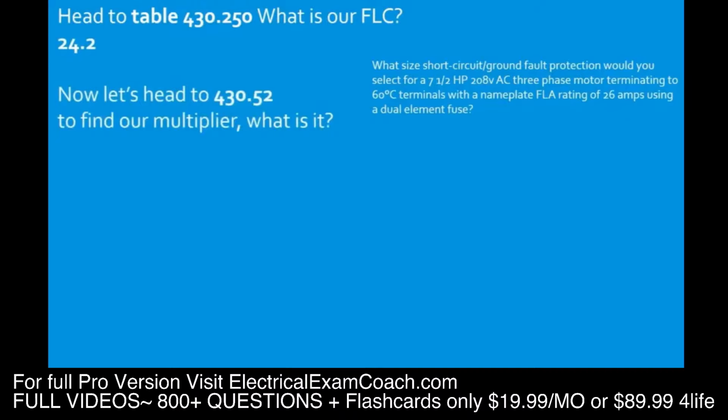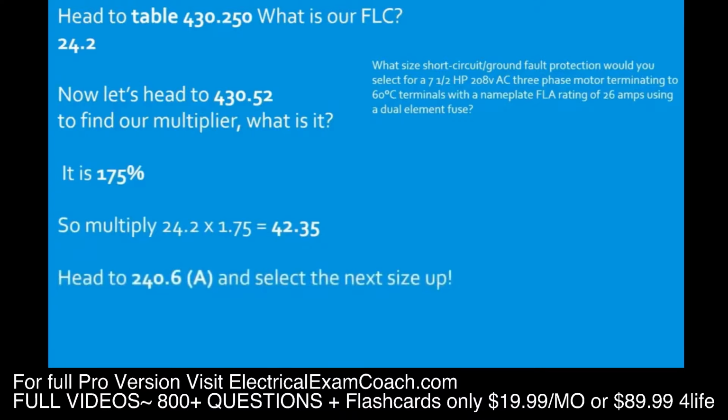Starting on the left for polyphase and then coming over to our type of device, we're going to find that it's 175%. We take our FLC, multiply by 1.75, that's going to give us 42.35. Now we head to table 240.6(A) and select the next size up. And we select B.